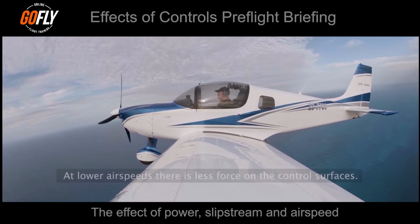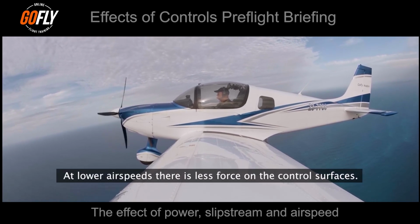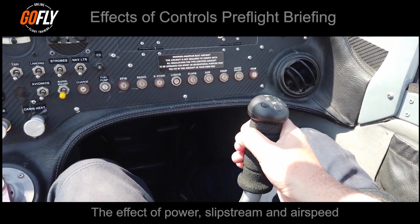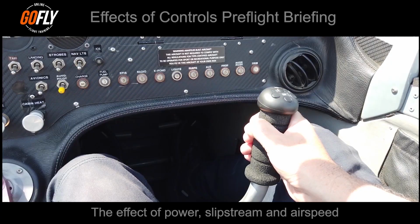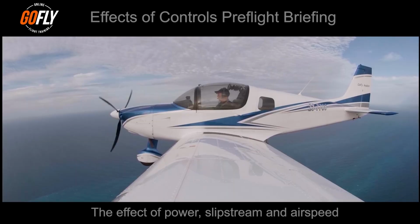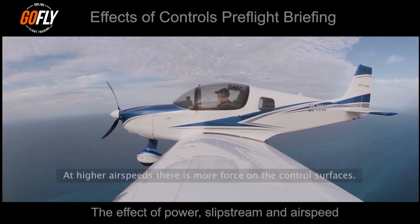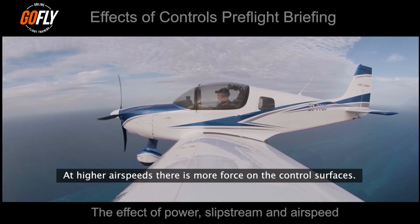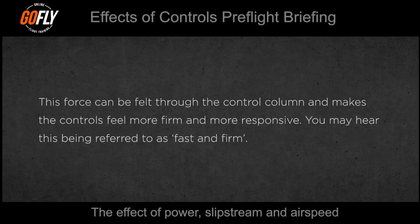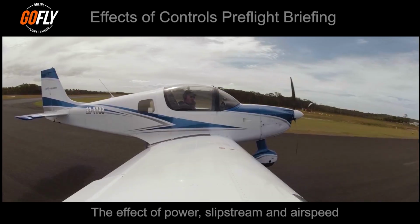When an aircraft flies at a lower airspeed, there is less airflow flowing over the aircraft and therefore less force on the control surfaces. This causes the control column to feel less firm and less responsive. We call this feeling sloppy or sloppy controls. When an aircraft flies at a higher airspeed, there is more airflow flowing over the aircraft and more force acting on the control surfaces. This force can be felt through the control column and makes the controls feel more firm and more responsive. You may hear this being referred to as fast and firm.